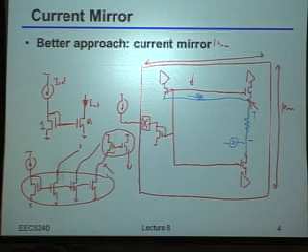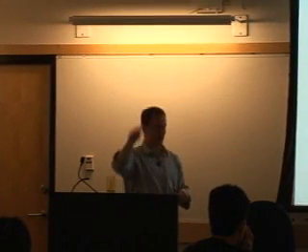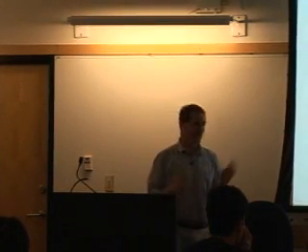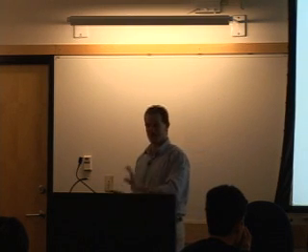What you actually do is you shield it with metal around it, right? And in fact, you can even build little Faraday cages around the wire where you'd have the wire in, let's say, metal 2 or metal 3. You'd have a shield of ground or VDD, depending upon what it's referenced to. Let's say the wire itself was in metal 3. You'd put a shield underneath in metal 2. You'd put metal 3 wires with vias both up and down right next to it. And then you'd put a metal 4 on top of it to create a little cage around the whole thing. Okay? And in case you think this is kind of wacky, trust me, this is done for real.